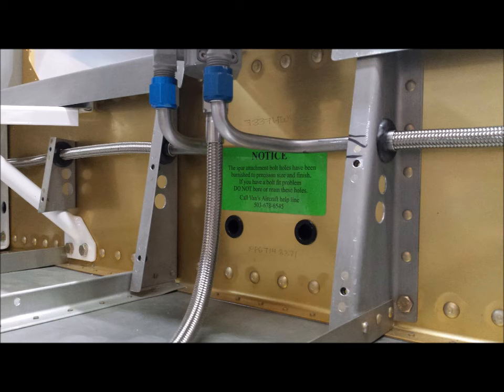After we're done machining the ends, we take the rigid tube over to our CNC bender, and just like in the previous video, we make the appropriate bends. When we're done with that, we flare one end of it and then crimp a flex hose assembly onto the other end of it, and that's how we make our custom RV7 and 9 rigid to combination flex hose assemblies.